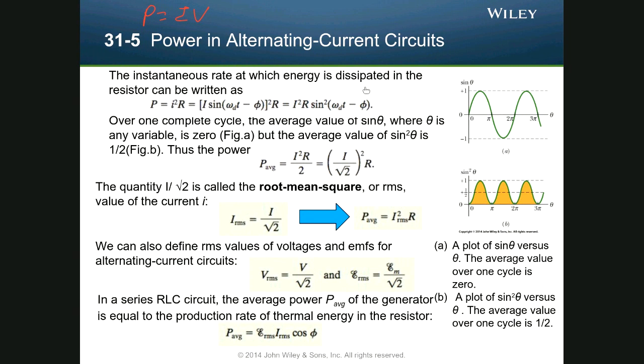When we look at averages of our voltage, right? If we just look at I average and V average, that could be a problem because both of those will be sine or cosine functions and they average to 0. And anyone who's plugged into an AC outlet knows that the average power is not 0.